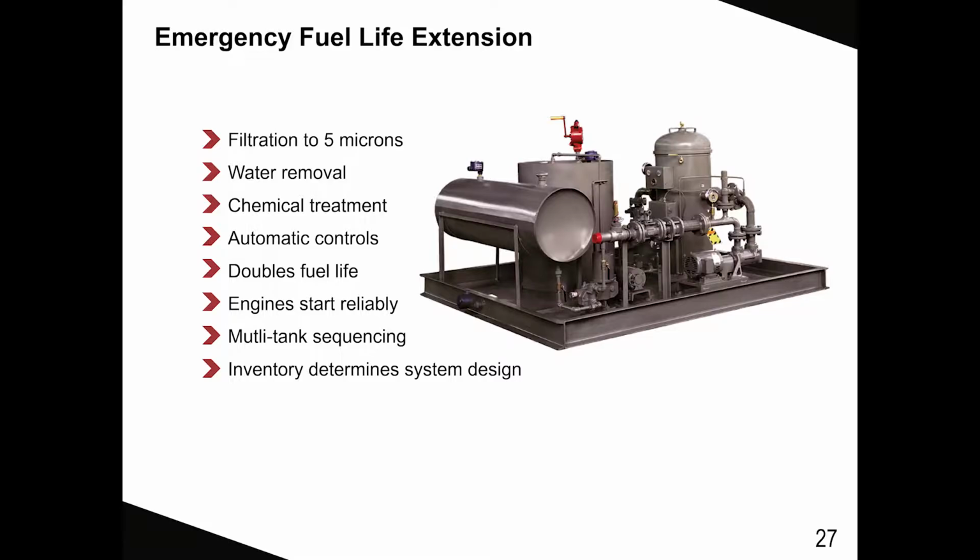And so, Ed, looking at this large filtration unit here, you have a horizontal tank, and you got this vertical tank with a hand pump, and then to the right of that, another cylindrical tank. Well, the cylindrical tank is where your filter cartridges are, with the high pressure lid with the ASME lid on it there. The tank closest to us is a biocide tank, the horizontal tank, for injecting a biocide to help stabilize your fuel or lengthen its usability.